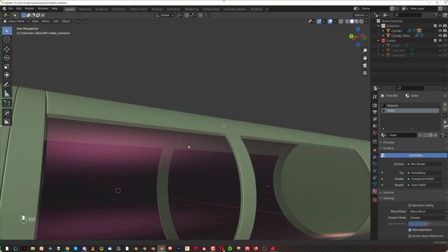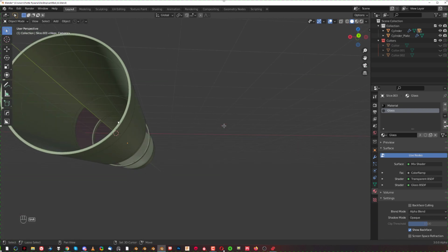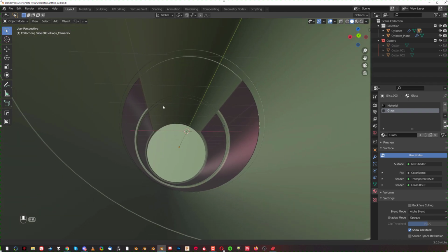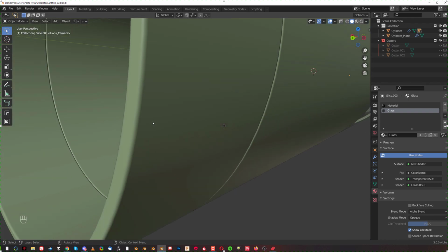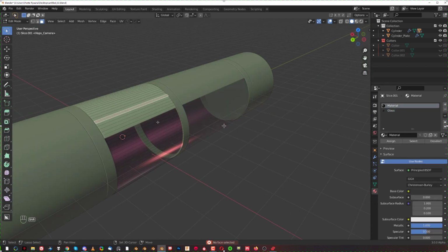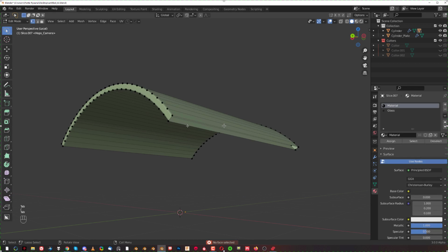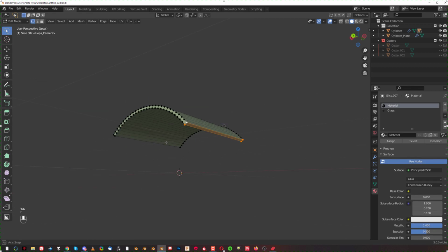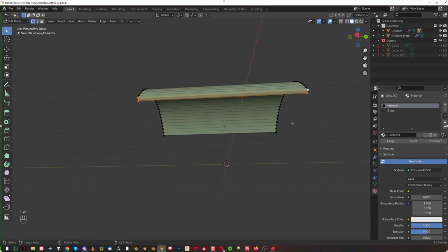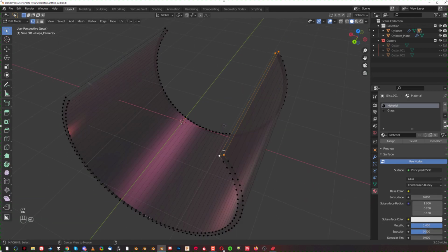Now what we could do is actually close this opening here with a face, and I think it's going to look a little bit better. So let's select the face, Shift G, select my material, and we're going to separate it to its own geo. So P to its own selection, and then close this face and close this face, and grab this glass and do the same thing. So here, close the face and close the face.